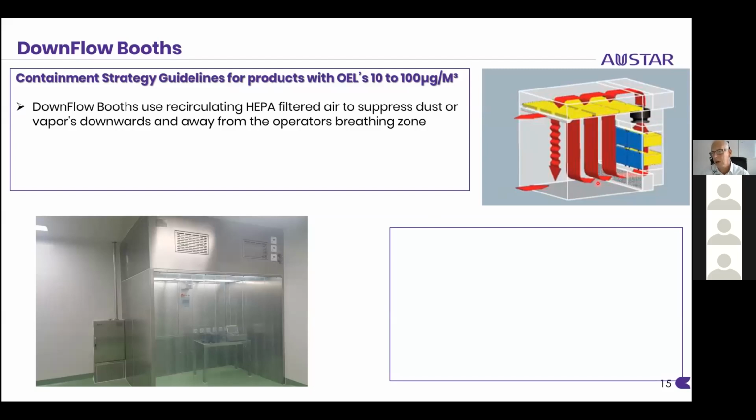It recirculates from that fan, delivers into a ceiling plenum, and then through distribution screens, usually HEPA filters, it pushes the air down at a very, very steady volumetric velocity. And if there's any dispensing or powder generation here at the source, it removes it from the airstream purely by the dynamics of the air, and then takes it away into a filtration system.